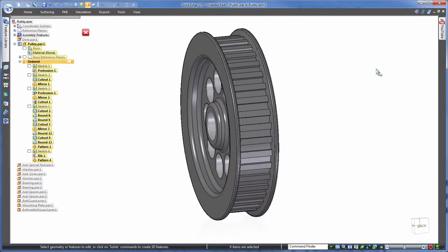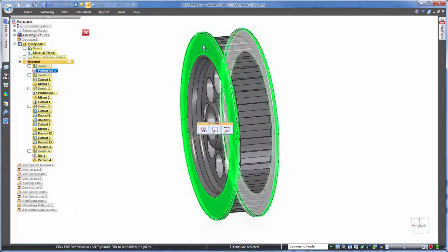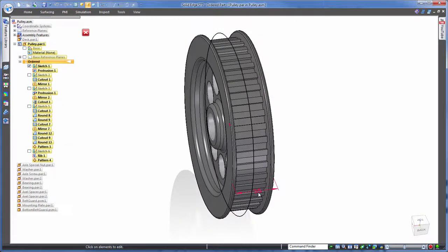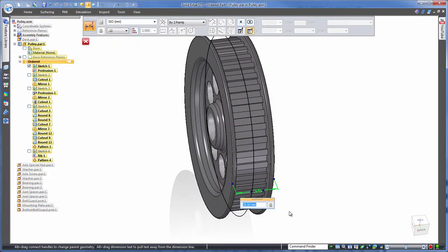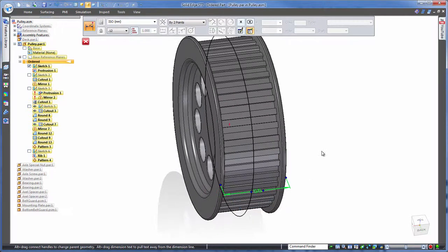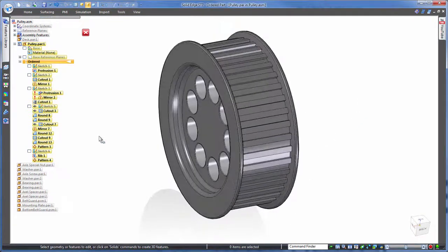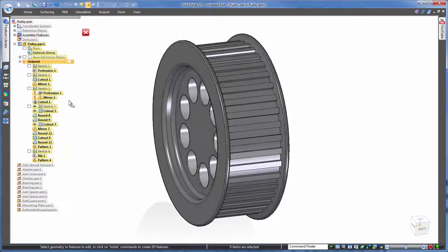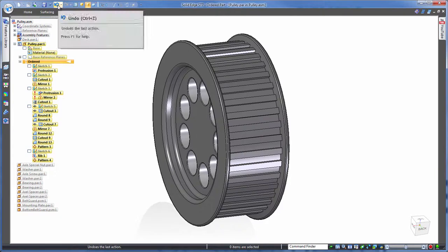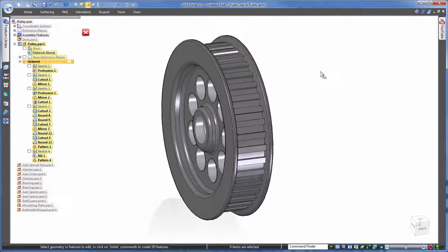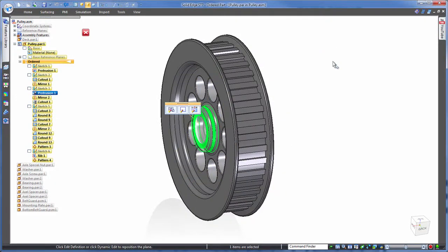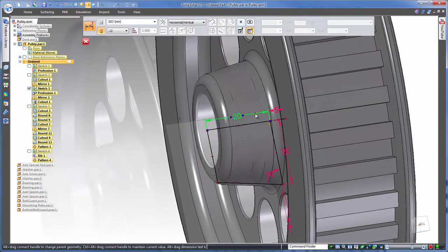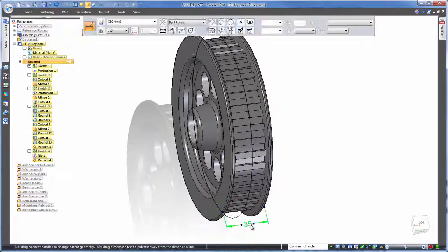It can be tricky finding which feature is the one that we want to edit, however Solid Edge does assist us by picking up the relevant feature after we click on the model in the graphics area. So let's take this 35mm dimension and change that to 55mm. Simple. Oh no, wait. Because this is history-based editing, there are dependent features further down the tree on the left that this has caused issues with, damaging our model. So we need to go back and work out how we can make our desired width change another way. It turns out that we need to make multiple edits to not very obvious features in a particular order.